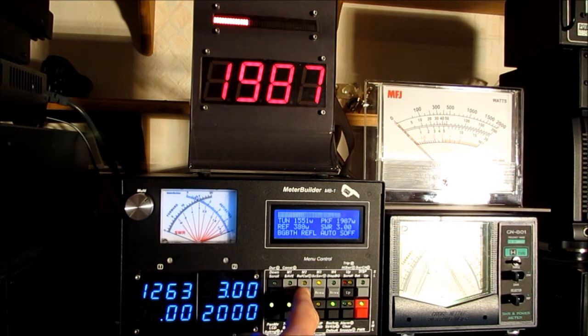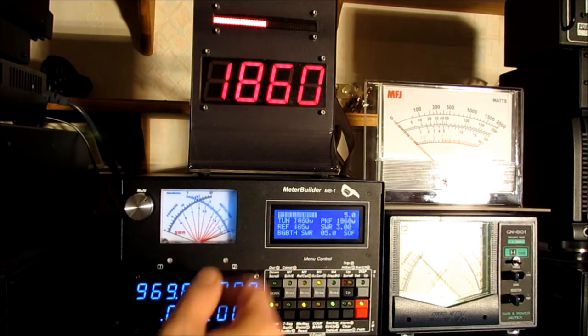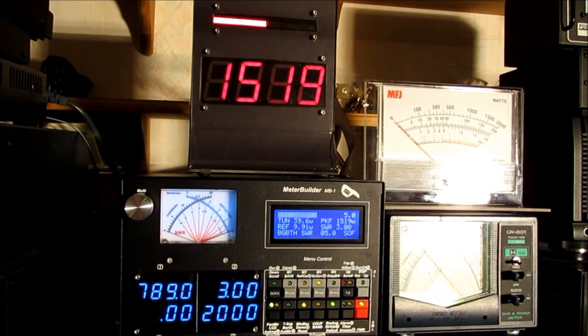Let's continue. Reflected real time, delivered real time, SWR. Okay, I've got a constant SWR of 3. It turns out that the SWR feature makes use of manual ranges and not the Automax. We explain in the manual why it didn't quite make sense to do that for SWR. But for all other parameters, the Automax function can be used.